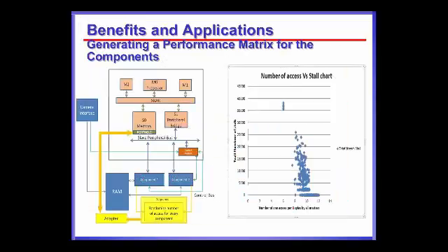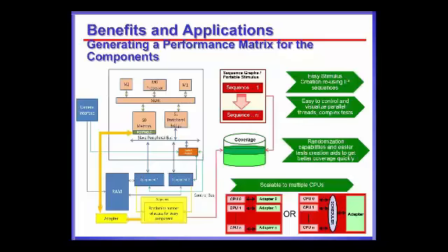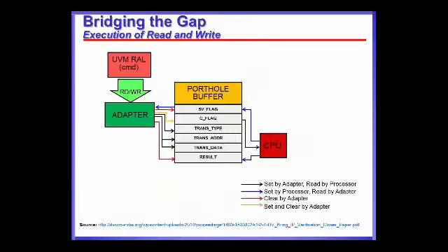Yes, so let me try to explain that. In terms of performance, there is hardly a penalty because it's not post-processing that we are doing. What we do here is, on the fly during runtime, as soon as there is a transaction through UVM RAL, it is converted into an instruction for the CPU to execute. The CPU will take that instruction and execute it just as it used to when hex was loaded in the memory, because even then it has to do a read to fetch that instruction from memory and then execute it. Now also it will do the same.